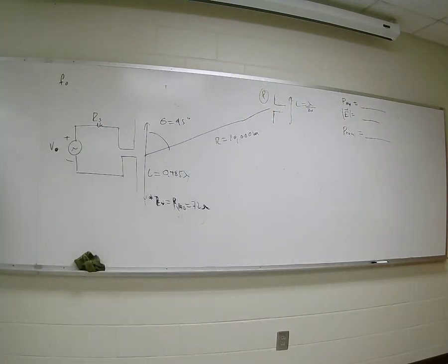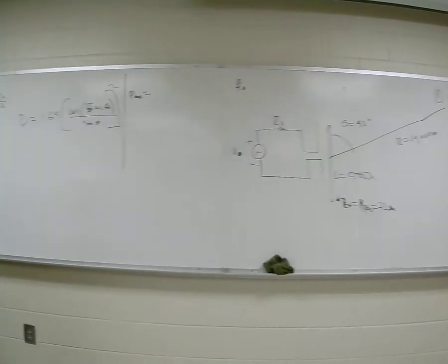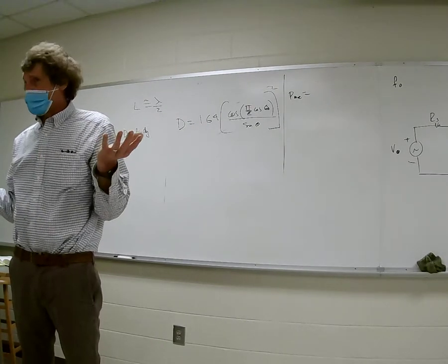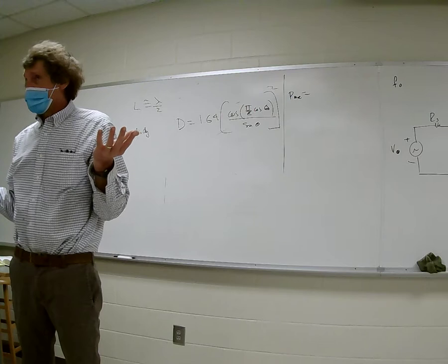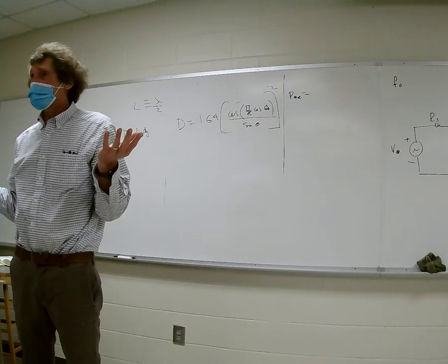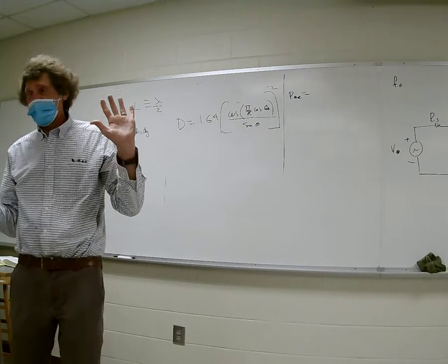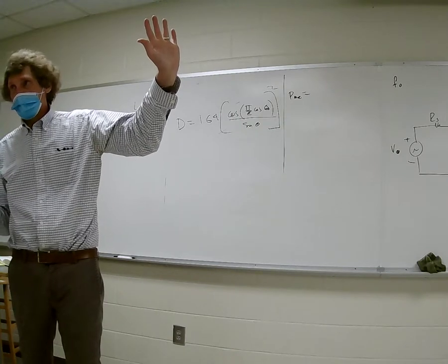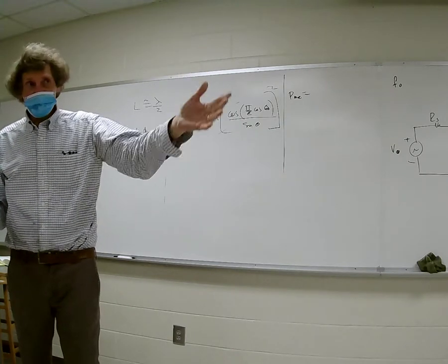How do you get P average? That's the average power density. What do I need to get that? In a nutshell, what would I need? The total radiated power, right? Then I have to divide that by 4 pi r squared, don't I? That's the average power density without any sharpening or any focusing, right? Then I have to multiply that by the directivity.